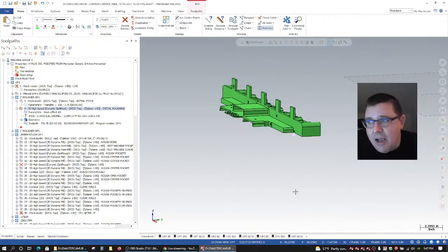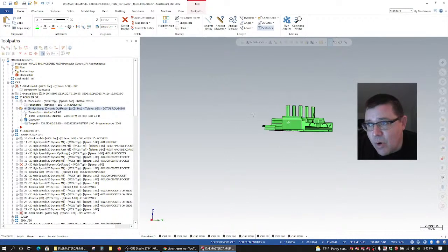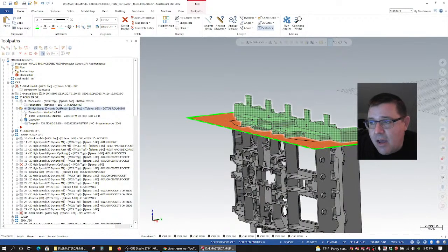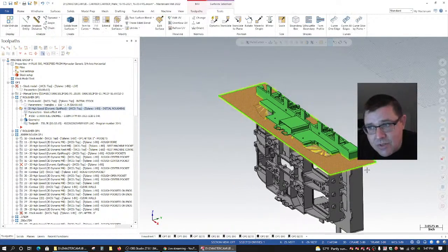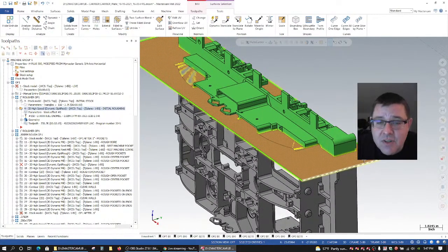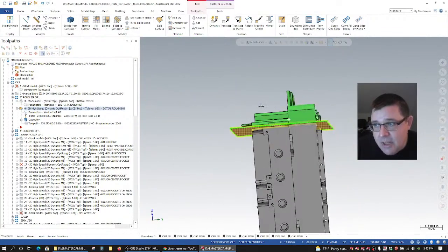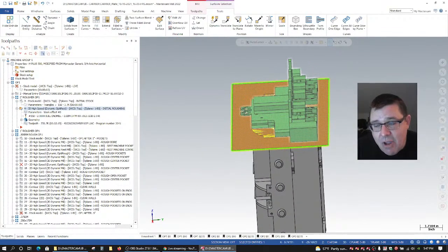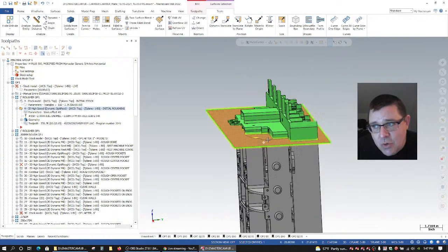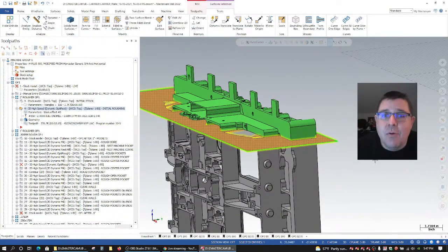Yeah, anyway. So splitting a solid is a great technique if you're just working on one little edge of it. Otherwise, creating and using run-out surfaces, or a patch surface laid over a bunch of features, is a perfectly great technique to focus the machining not only in a certain area, but only down to a certain depth, coming from one direction. So yeah, that's also a great technique.